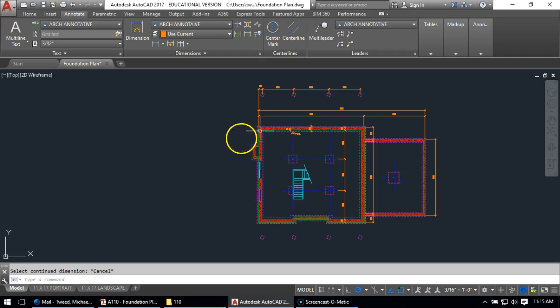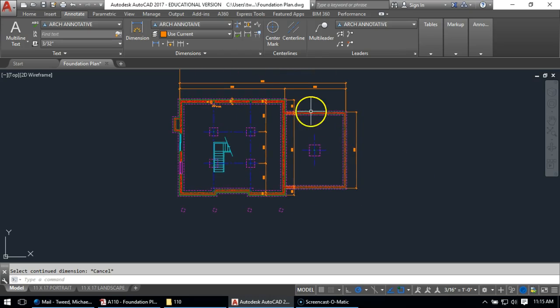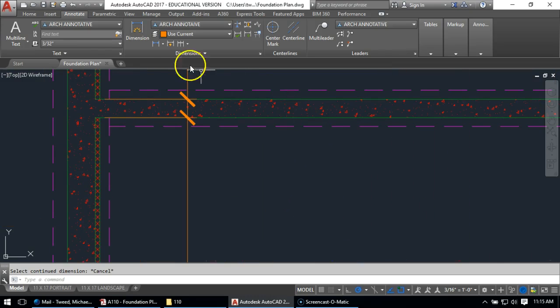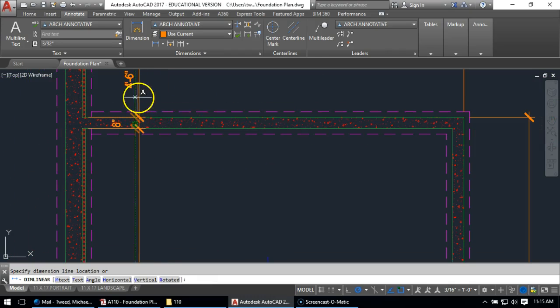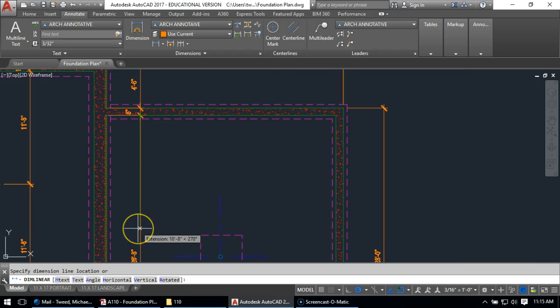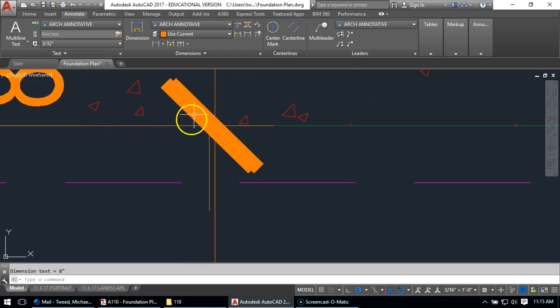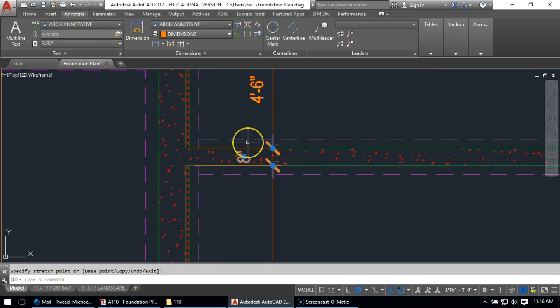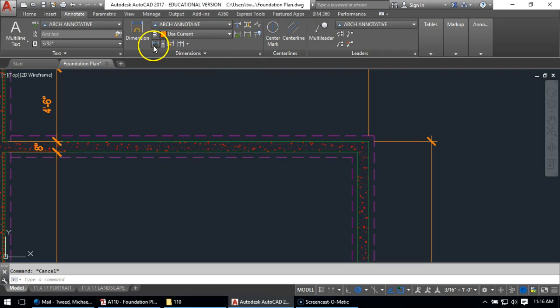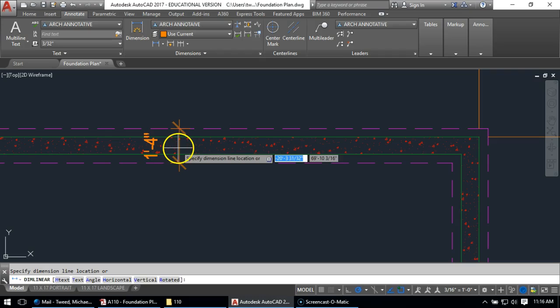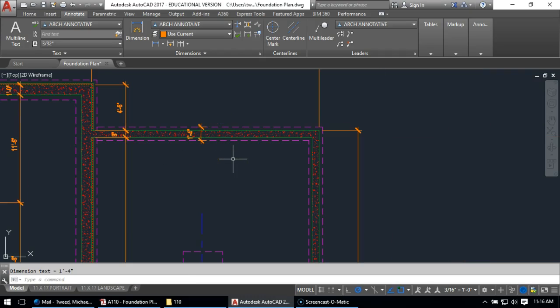There, let's see, most of the top is done. I started the garage in definition, so let me show some of the things here. I'm going to do the wall itself from there to there. Right, I can just select those 2 points and snap in to get those aligned. Not quite aligned, so I can always select it and move it back into place if for one reason or another I missed. There's an 8 inches there, and then over on this side I have 1'4" for the footing dimension.